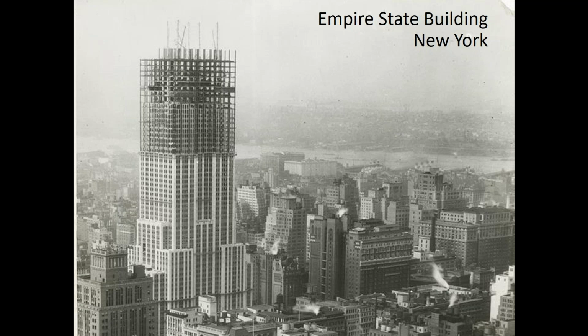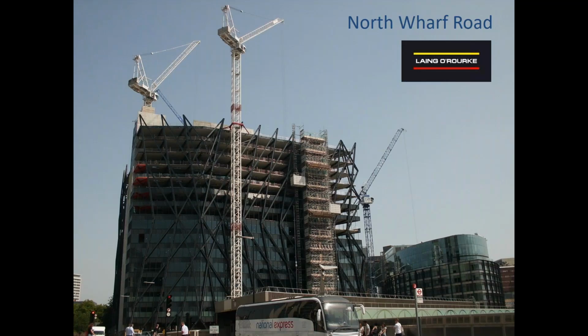But as I said, nothing obvious in terms of a high capacity, heavy craneage. And there's another option which is used typically in medium rise construction, sometimes also in high rise construction: mounting a crane on a core, but a core that's finished, that's reached its peak. And that's what you can see in this photo. This is a Langerock project finished about 6 months ago, an office building near Paddington in central London.